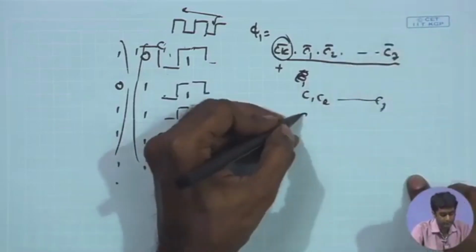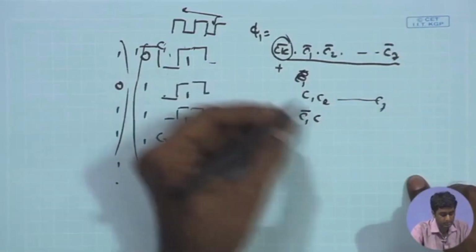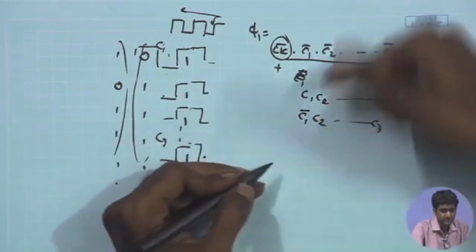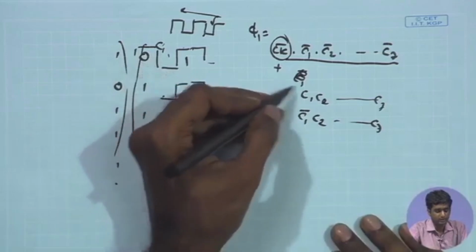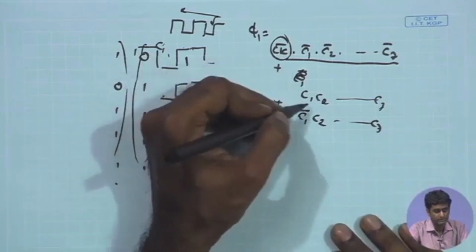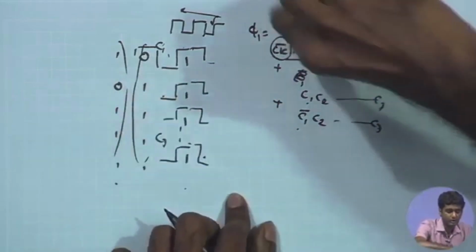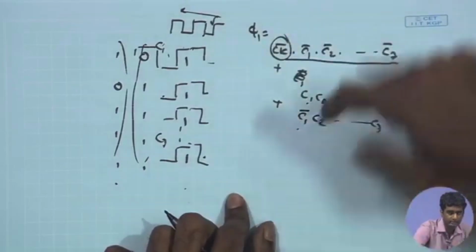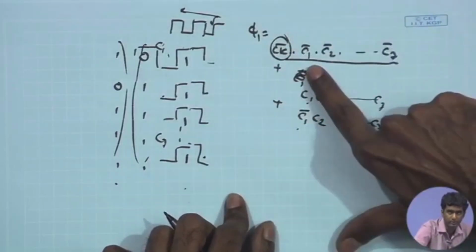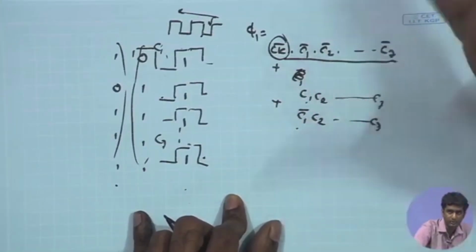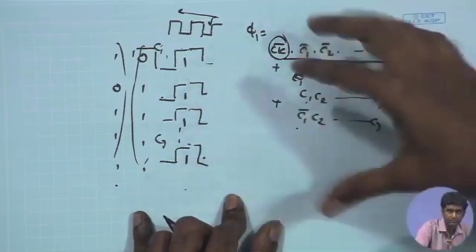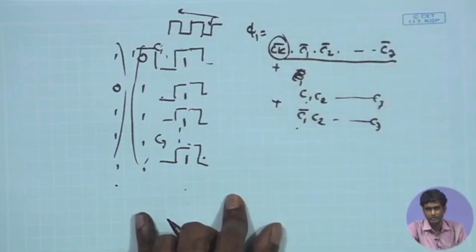Before that you will have the phase C1 bar C2 up to C7 preceding just this one. So, suppose for these 3 phases I would like to keep the phi 1 high. So, I will just take the OR of this, this and this. Therefore, you compute this particular logic using an AND function, another AND function to compute this particular combination, another AND function to compute the third one, and you OR them together, and therefore, the phi 1 will be remaining on for that entire duration.